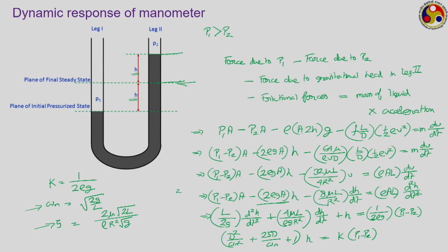So, a simple U-tube manometer can be viewed as a second order instrument with this particular form. And this way we can perform any kind of dynamic analysis, just the way we perform it for any second order system. Like a manometer which is initially under steady condition, maybe having equal height of fluid column in both the columns, if it is suddenly subjected to some kind of ramp input or just a step input, that is, suddenly you impose a different pressure on both the arms, how is that going to behave? You can easily do this by comparing with the corresponding reference equation.